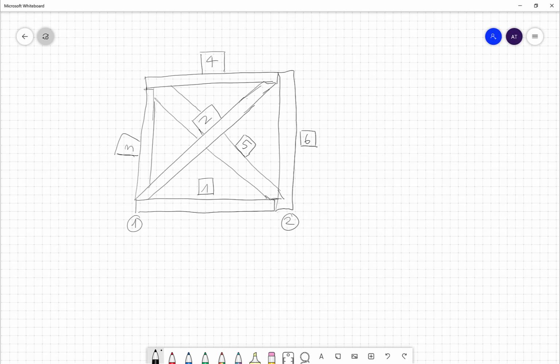Nodes are specified within a circle. Near and far ends are indicated by the arrows along the members. Each degree of freedom is a displacement. There are 4 nodes, with 2 degrees of freedom per node, so there are 8 degrees of freedom for the truss. And so the global stiffness matrix K will be an 8 by 8 matrix.